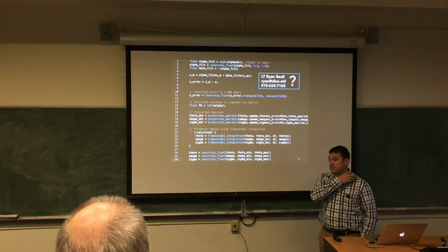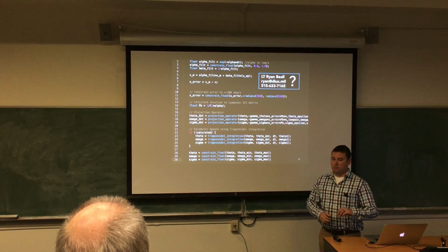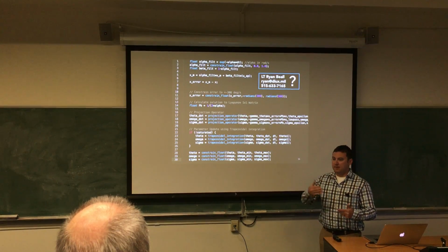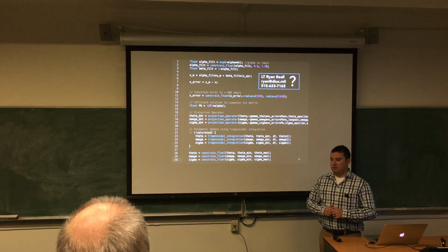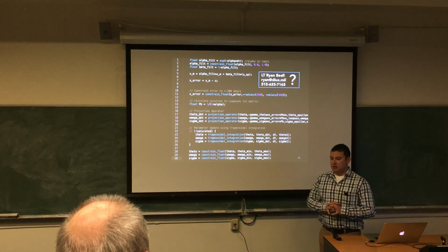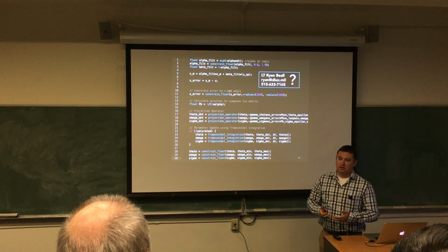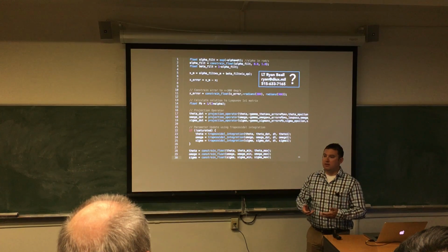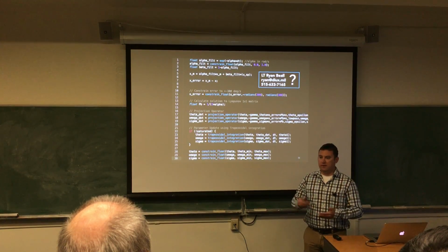So in the case of flap deployment, I would deploy the flaps and not touch anything else. So the flaps get deployed, flaps come down, and then I would just watch the pitch and pitch rate of the autopilot. And then what made the testing really fast in flight was on the transmitter. I had 2 switches that I could toggle for adaptive control on or off for pitch and then roll.